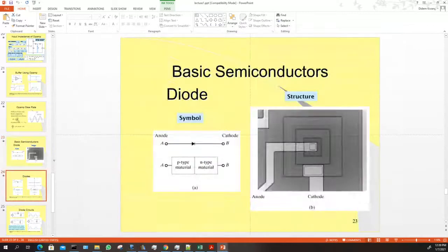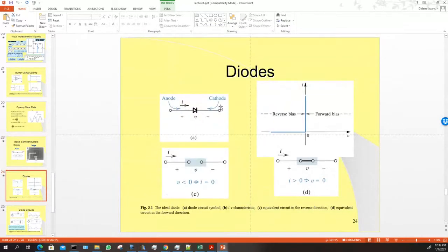So most generally, we'll say with diodes the current will go in this direction, but never in the opposite direction. If your current is going this way, it's great. The diode is just removed and you put a straight line there. It's just a wire. But if the current starts to go in this opposite direction, it can't. It's like a one-way street. The current can't go in this direction, so therefore it's like an open circuit.